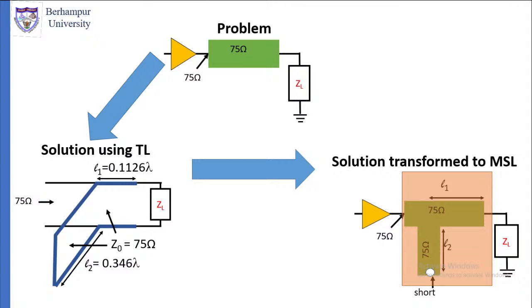For example, suppose we have a coaxial cable. At the end of the coaxial cable we have a load. Now from a distance of 3 cm from the load, we have connected the stop. After calculation, we have found out that the distance from the load is 3 cm. In terms of wavelength we have calculated it, and then from wavelength we have calculated it in terms of centimeters. So 3 cm or 5 cm from the load end, we have found this.